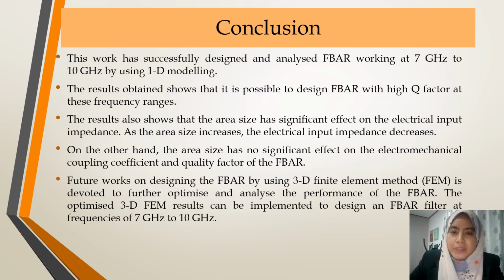So now we are on the conclusions. This work has successfully designed and analyzed FBAR working at 7 GHz to 10 GHz by using 1D modeling. The results obtained show that it is possible to design FBAR with high Q factor at these frequency ranges. The results also show that area size has significant effect on the electrical input impedance. As the area size increases, the electrical input impedance decreases. On the other hand, the area size has no significant effect on the electromechanical coupling coefficient and the quality factor of the FBAR.